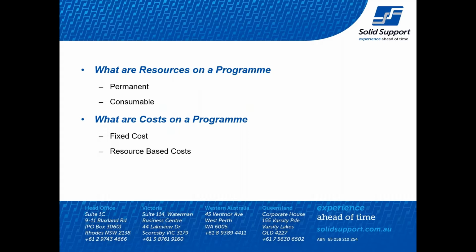So that's what you're doing here. If you need to cost load a program, you can do that very quickly and easily inside Powerproject. If you're looking to base it on the resources, you can do that as well. Very easy to set up the rates, and you can do a mixture of both, so have fixed costs and so forth.